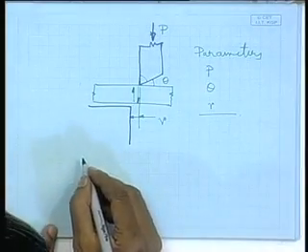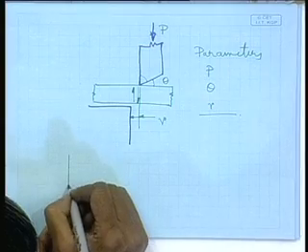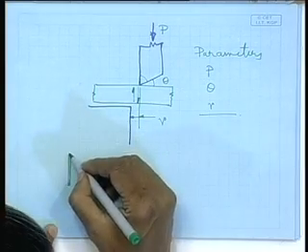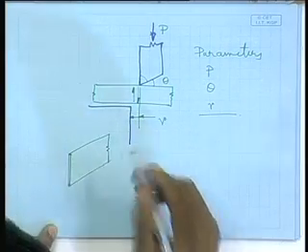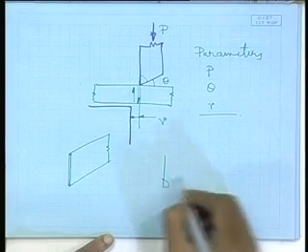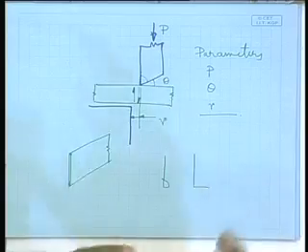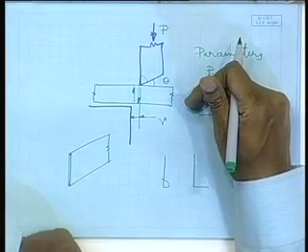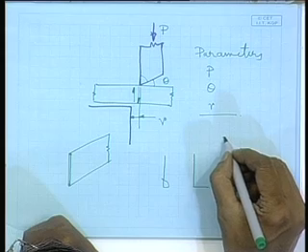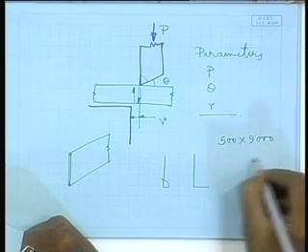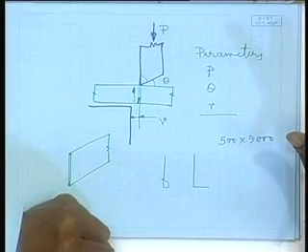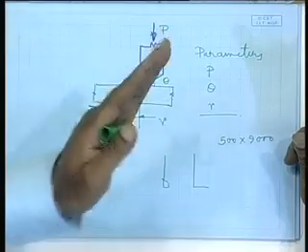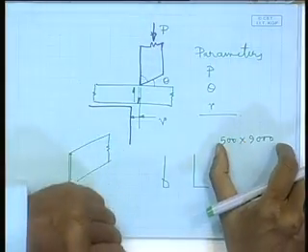Now, as I have already told you, one of our stiffening members is the flat bar, isn't it? Now, these flat bars, if it is a standard dimension, then they are available. Available means like your so-called bulb section or angle section, some of the standard sections are available. But if it is non-standard, some flat is needed, then this shearing machine is ideal. Suppose some 500 by 9,000 millimeter rectangular strip is needed. So, you put a plate, right, get this 500 measured, and in one stroke you have that plate.